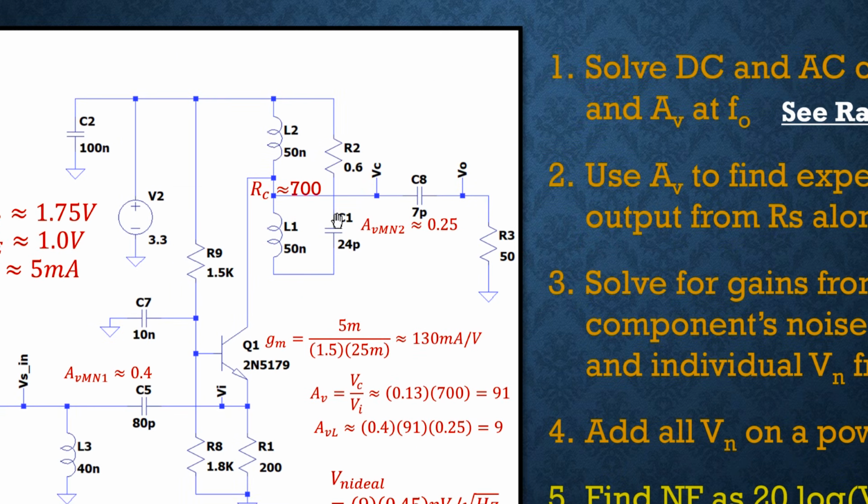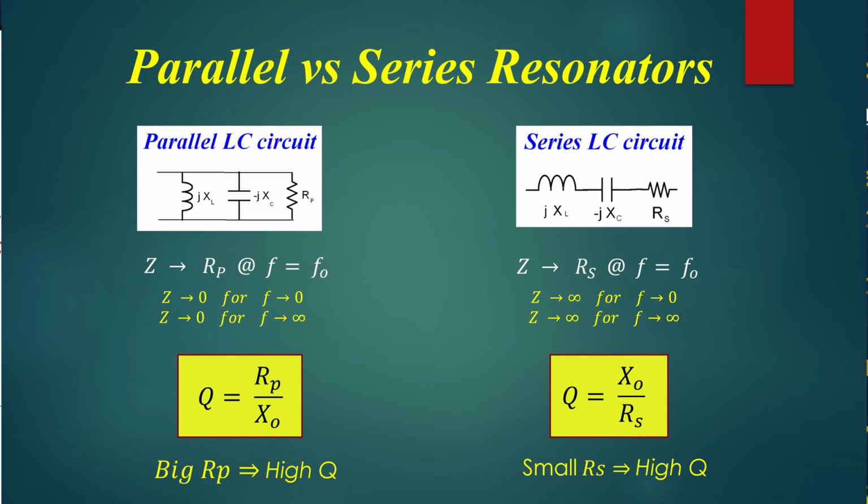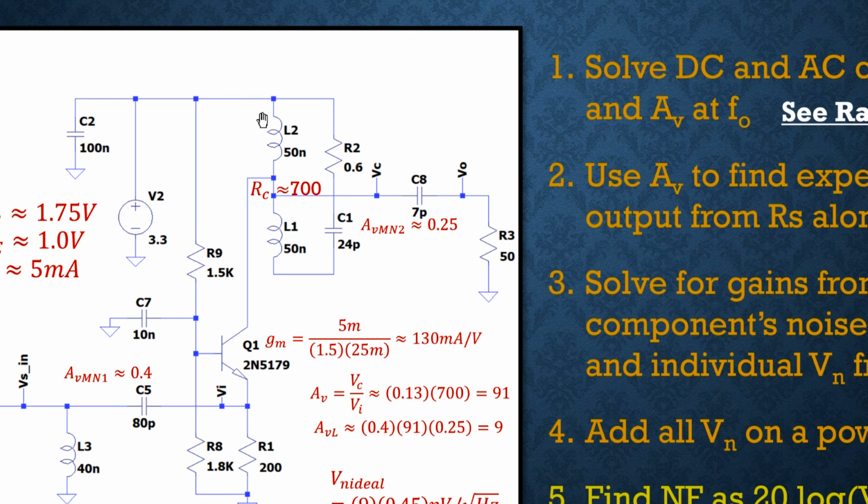Going back to Radio Design 101, we know that for a parallel LC resonant circuit, we have to have the quality factor. And if we have that, we can figure out what the net equivalent parallel resistance of this is. There's some losses in it, which here is captured in a loss resistor R2. So that models both any losses in the capacitor, which is usually pretty small, and the quality factor of the inductance, which for the inductors that I used in this circuit ended up being close to 100. So that's where the 0.6 came from.